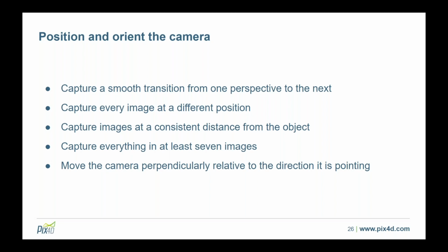Please note that, considering that the Helios 2 captures video, it is possible for you to actually have too many images. Because if you were to extract every single frame from the video, you would have numerous images that were captured at practically the exact same position. Therefore, you need to find a reasonable balance between capturing enough images, but not so many that you are not satisfied with the results that you're getting.